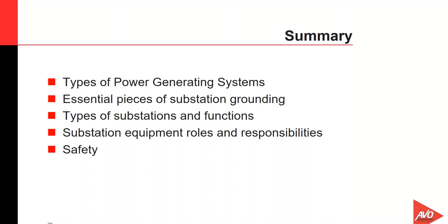We talked about grounding and the different types of standards that you could see out there in the field to help you maintain and install your substation grounding systems. IEEE standard 80-2000 was one that I used for conductors and connections. I also talked briefly about IEEE standard 837-1989, and then of course we dipped into the National Electric Safety Code as well.